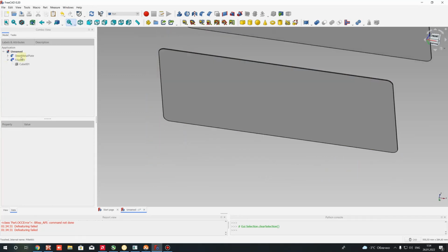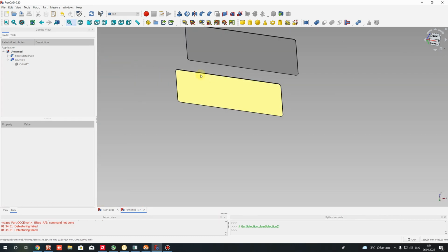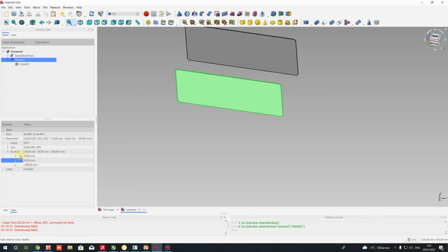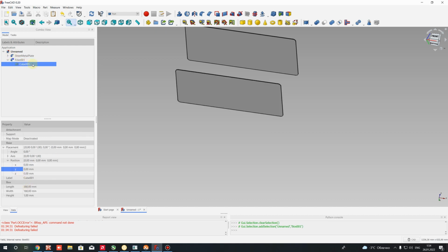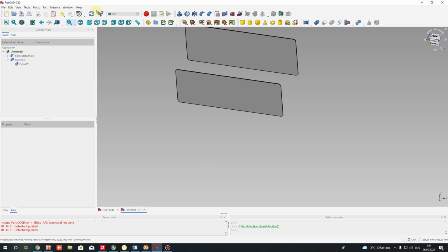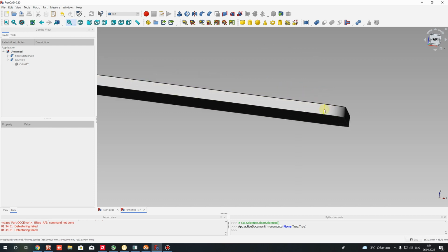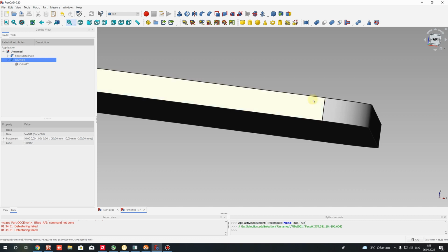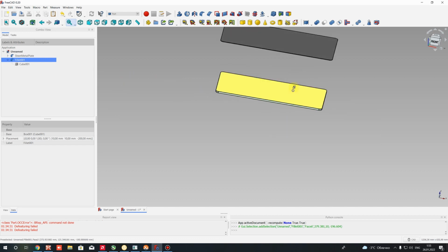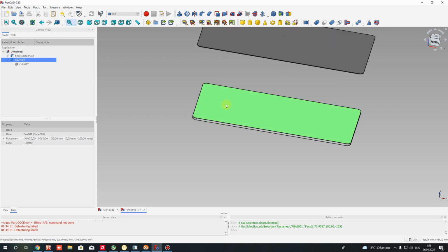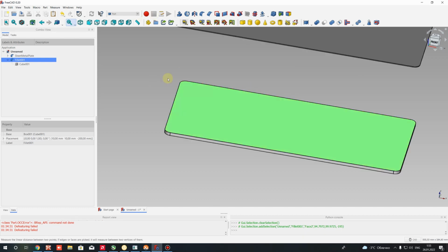After that, let's change the thickness of this form plate. I will change the thickness here in Cube001. I will set the height to 5 millimeters. We recompute it, and I will get this higher value of thickness. So after that, let's choose this face, and on this face we will create some forming parts for our kitchen sink. Let's choose this plate.